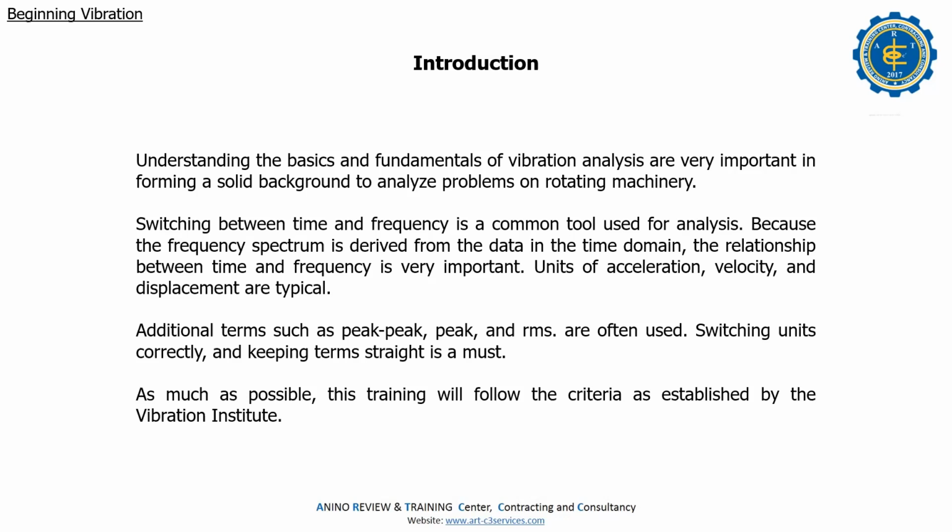So you make a report daily, right? No, sir, we have to make the report every one day. We have one software where we have to enter our vibration value, your analysis report, your comment, and what action you are taking. Whatever action we take, we make it as a notification and upload it in the SAP.